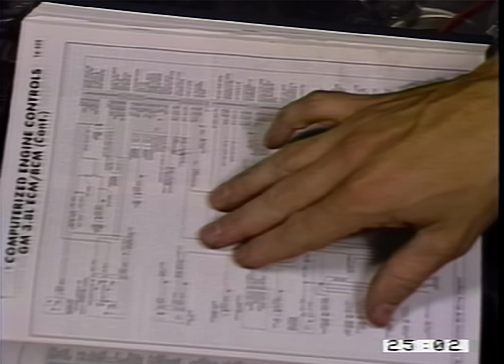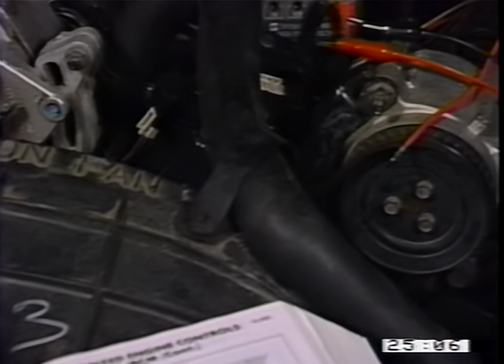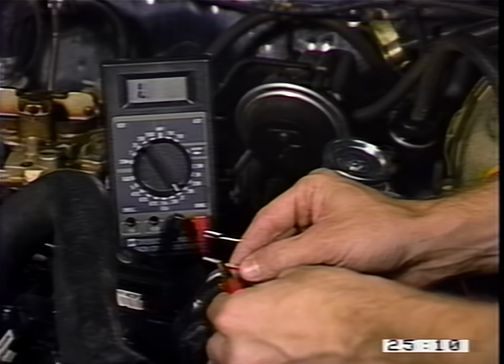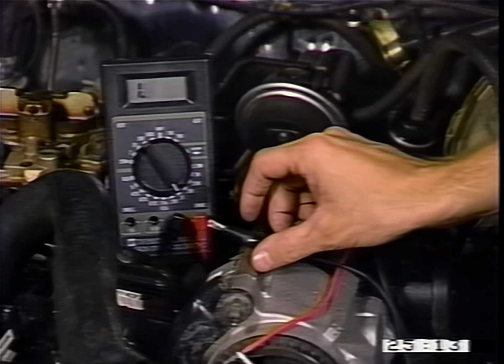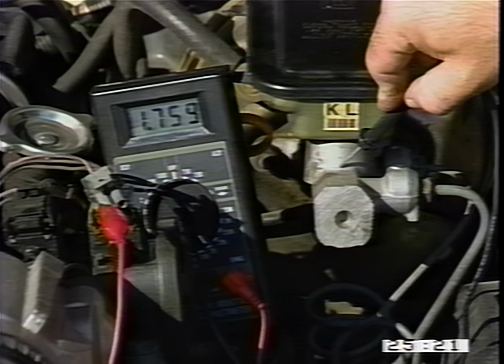Wiring diagrams having connection locations and resistance values are used to verify circuit condition. Next, the system circuits are checked by disconnecting wiring at both ends and measuring resistance to specs. If more than 5 ohms are measured, then wires need to be either cleaned or repaired. The ohm meter is then connected between one end of the wire and ground. Several 100,000 ohms resistance should be found. If not, the wire is considered shorted and has to be repaired.